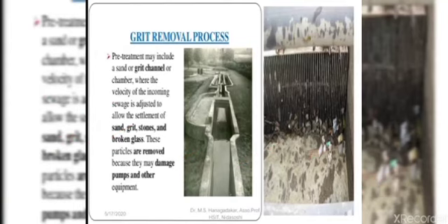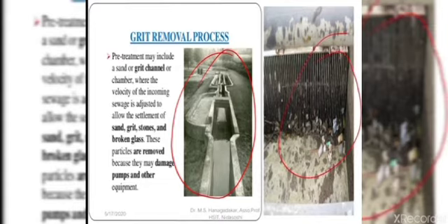That's what I can say, the grit chamber or screen chamber. Here, this is what I have shown in this figure. It is called grit removal. In this pre-treatment of grit removal, you can remove the sand and any heavy components like grit, stones, broken glass, etc. They can be removed by allowing the water to pass with low velocity through the mesh screen or bar screen. That's what I explained here. Thereby you can remove a large amount of components which are settleable.